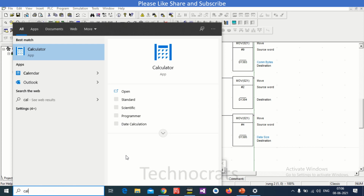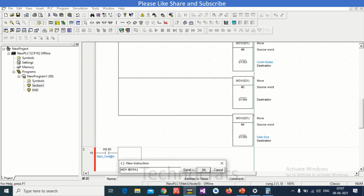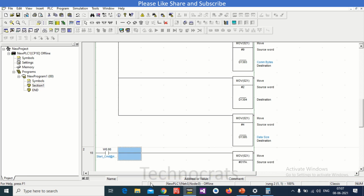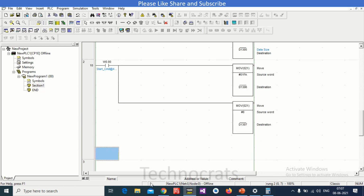What was that on the calculator? 40.00 is FA. Okay, so I will use FA here, D1306. Okay, with this, the second part of your frequency, MOV. Now it is I think D1307, #0. So this is your start command at frequency 40 Hz.